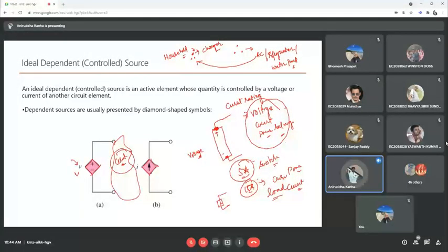So, in order to withstand the high current or the higher power dissipation, you need to connect to the 15 amp switches. If you simply connect your AC with the 5 amp switch, definitely it will trip. The main switch will get tripped. How the tripper works is a different part, but this is the general idea.